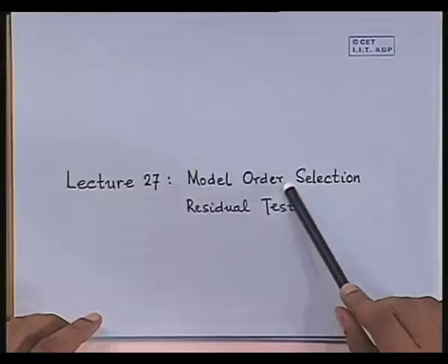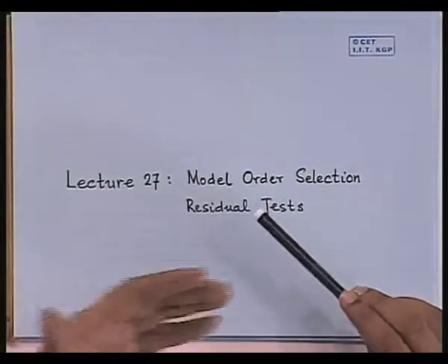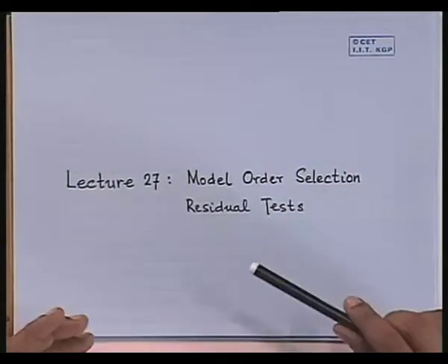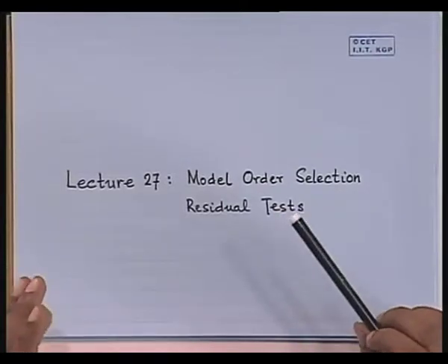That's why I have used the term model order selection. I am not saying model order determination, because it's not that you can nicely solve out that the model order is going to be 2. Rather, you have to select whether selection of a model order of 2 serves your purpose well, or selection of 3 is required, or maybe selection of 1 is sufficient. So in general, we would go by the simplest one that works for our purpose. It's more of a question of what works good enough for my purpose.